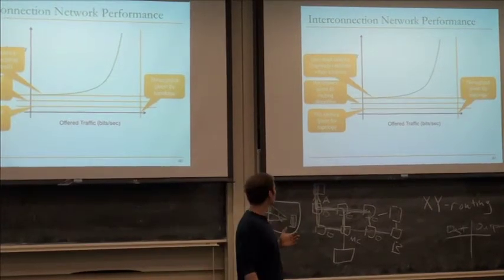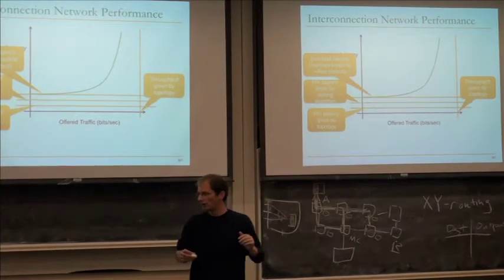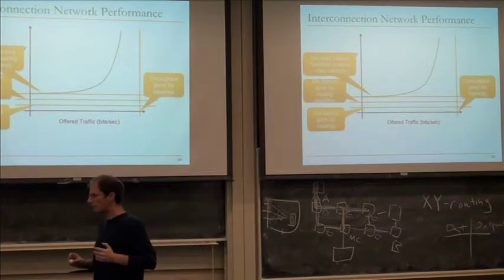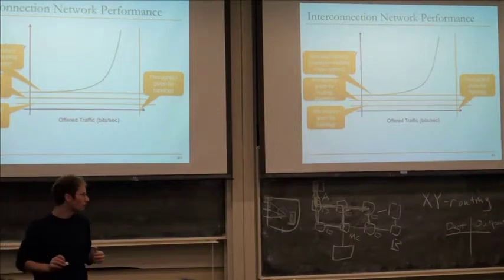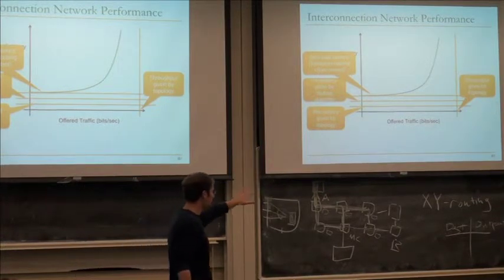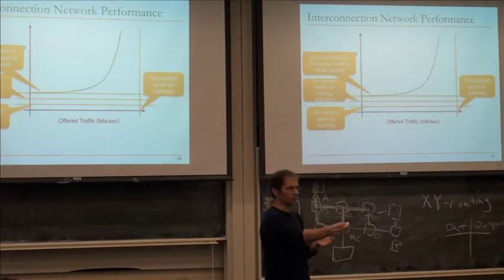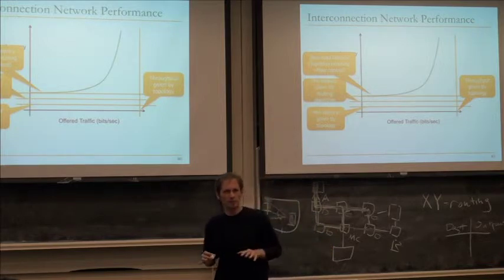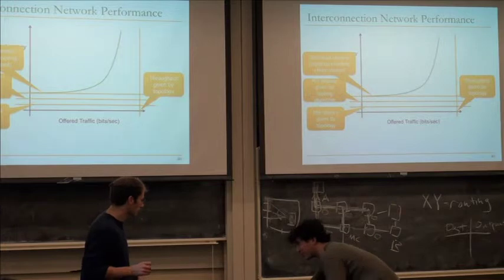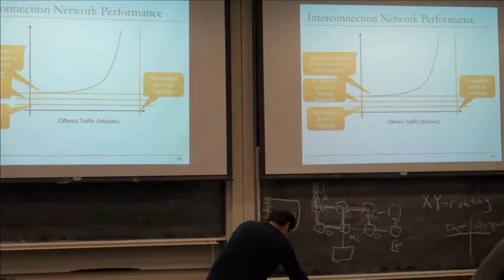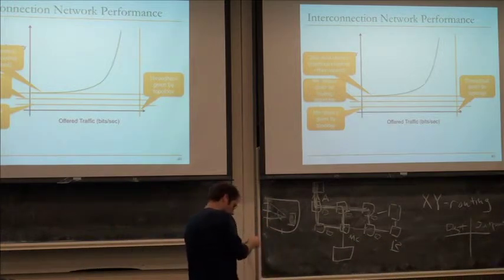Throughput, right? Before we talked about latency, now we're talking about throughput. The highest upper bound we could possibly hope for is the throughput given by the topology. So if you consider just the wires, the best you can hope for in terms of pushing bits through the network is keeping all of the wires busy in every cycle. Use all of the wires in every cycle.